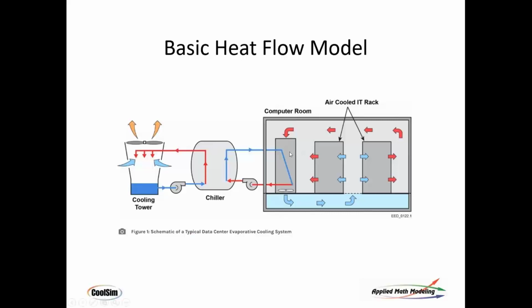And what you have here, over on the right, is the data center, and this is a downflow system, and you've got cool air coming in. I guess fat arrows mean air, skinny arrows mean water. So you have the air coming down through a fan coil with basically a heat exchanger in it, pumping cold water through it and getting hot as it goes, and it makes the air cold through the fan, coming underneath, convective cooling. These are mostly convective these days. A little bit of water, mostly convective, however, due to cost.